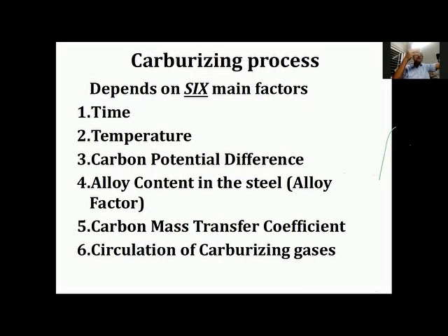Then you will go to maybe 900 or 910 for 0.5 to 0.8, and beyond that you can go to 930 or 935 or even higher. So temperature we can use to the advantage for reducing the time of the process and reducing the cost of the overall carburizing operation.